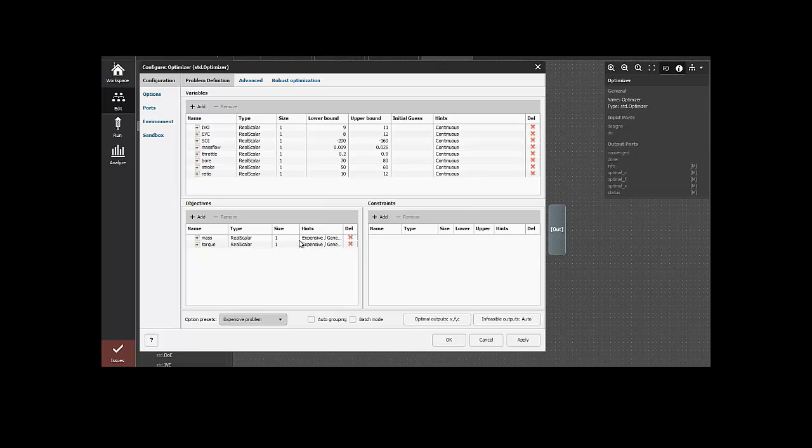Expensive is one of the most important hint possibilities, because it turns on the global search based on multi-objective surrogate-based optimization. When we create the approximation model inside the optimizer and improve it at each step to get our optimal point, or Pareto Frontier in this case, because we have these 2 objectives.